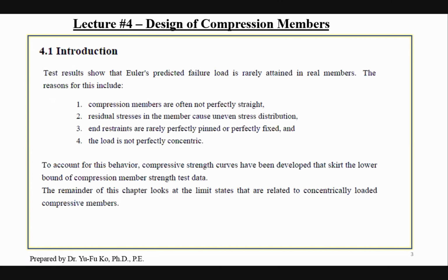And also the loads in reality are typically not perfectly concentric, meaning you're creating a moment at the end of the member. So to account for this behavior, a compressive strength curve has been developed that skirts the lower bound of compression member strength test data.